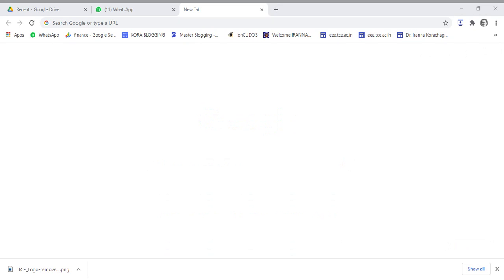So the second keyword is: apply rated current at rated frequency, keeping the contacts of the circuit breaker closed. Once we do this, we can see that current is now flowing, because of which there is heat generated because of the I square R effect, and that heat generated gets dissipated wherever it comes into contact.